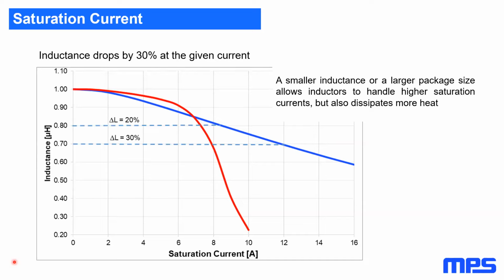Coming to an underestimated topic, which is the start of the winding. When designing a DC-DC stage, you want to place the converter switch node close to the start of the inductor's winding. Inductors don't have a polarity, as, for example, capacitors do. So why is the start of the winding important? The first layer of the winding, which is the inner one, gets shielded by the following layers.